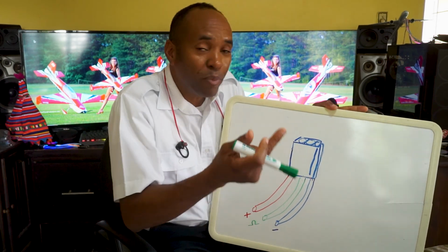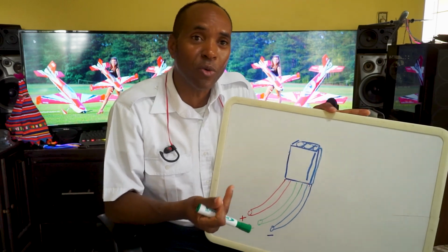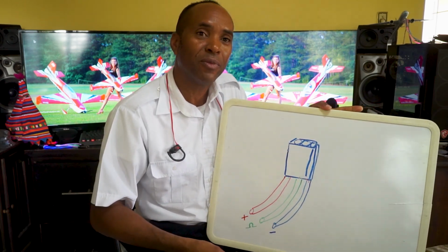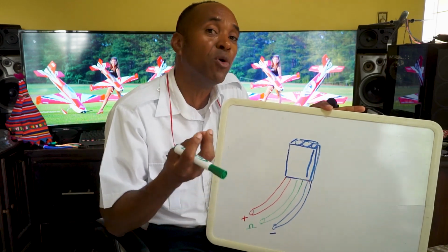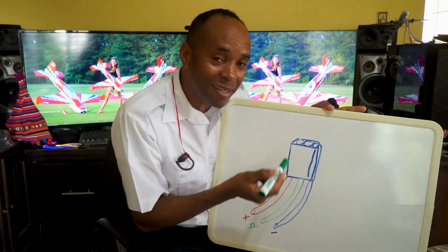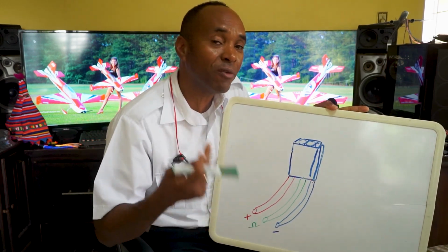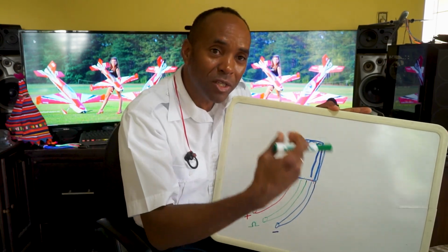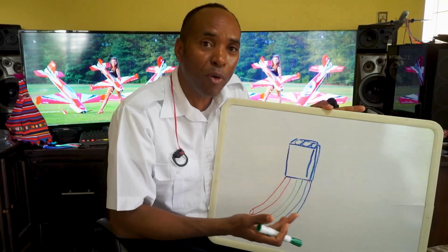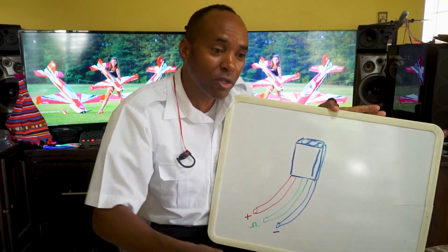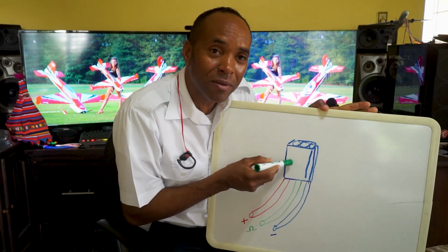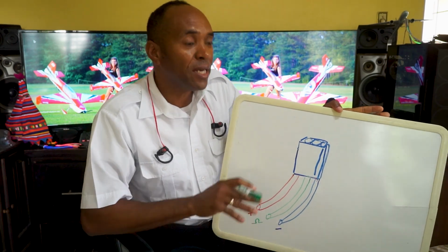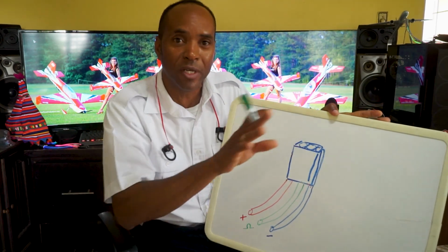For a big plane, from your battery to your switch, you're going to think about a Dean's connector or an XT60 or a JST connector, something more robust that can take 20, 30, 40 amps, right? You want a big size receiver now, or probably some kind of power bus to distribute out the current so that you don't have to run through this one, because this one will bring down your plane, see? And then the current will distribute out to everything else.